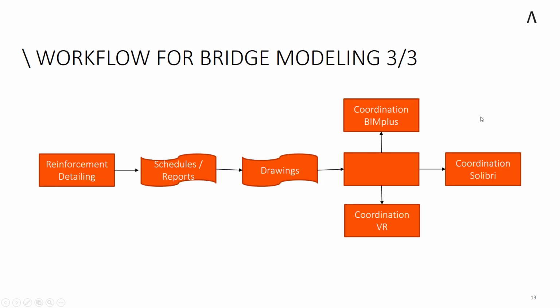The next main section of the workflow for bridge modeling, this is where we really do shine. Engineering has been considered at other stages in the process previous to this, but this is where the engineering really starts coming into play. Once you've got your model created, you can then populate it with reinforcement, post-tensioning, pre-tensioning, and then you can start to develop or generate your schedules and reports. And the nice thing about having the model is when any changes occur, your schedules and your reports are going to get updated as well for you.